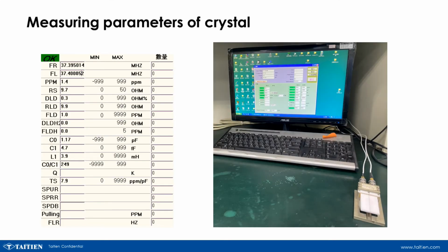In order to further understand the characteristics of crystals, we need to remove the crystal from the circuit and measure it. We use a network analyzer to measure crystal's parameters, and the equivalent parameters will be obtained.